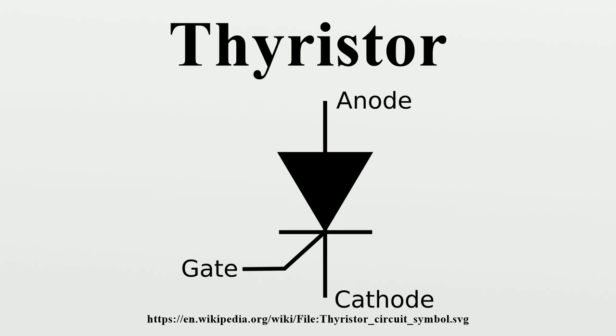In some applications this is done by switching a second thyristor to discharge a capacitor into the cathode of the first thyristor. This method is called forced commutation. After the current in a thyristor has extinguished, a finite time delay must elapse before the anode can again be positively biased and retain the thyristor in the off state. This minimum delay is called the circuit commutated turn-off time.